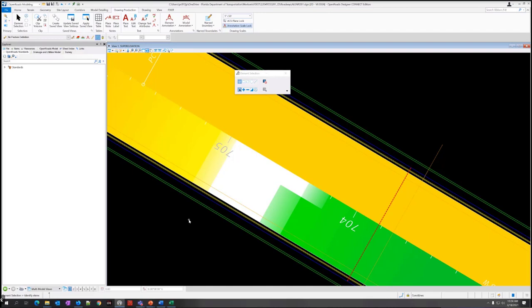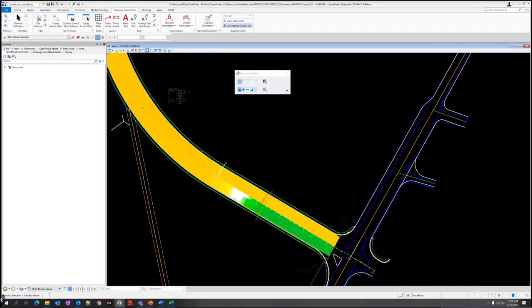All right, so this is exercise 3.7. We're going to add the super elevation lane for the curb. And you can do this for other lanes as well, if you made modifications after you created the super elevation sections and need to add another lane, or if you just don't have it in your corridor yet. You can do that. So we're going to the corridors tab, back to the super elevation section here, and we're going to create this middle one here, create super elevation lanes.